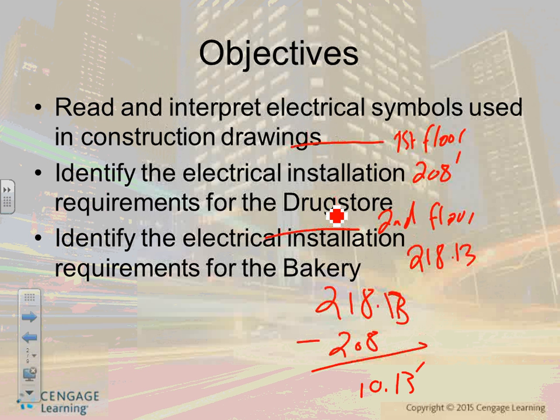So the first 6 sections are architectural. Why do we list them? Because it tells you the type of material that we're going to be constructing from. And I believe it's a commercial building. Typically most commercial buildings are either steel, concrete, or block buildings, right? Some commercial buildings are wood buildings too, so you need to know if it's wood. This looks like a steel and concrete building. So concrete foundation and steel studs in between.